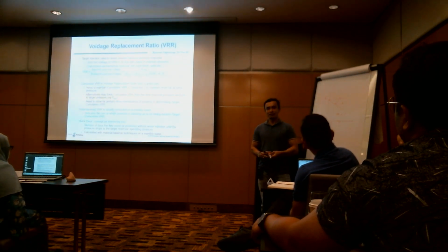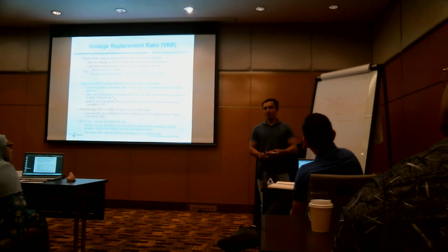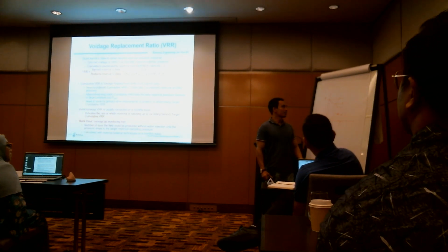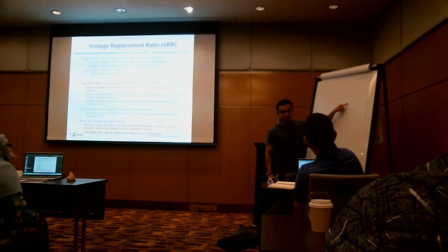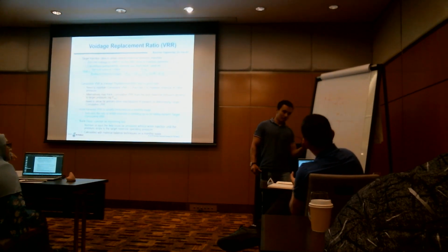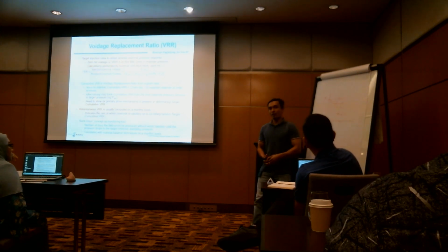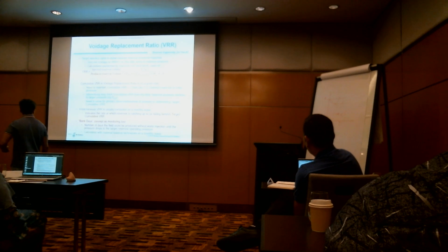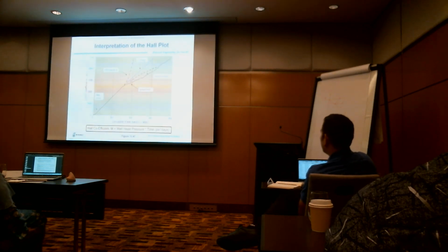So once you reach that original pressure, your cumulative VRR is about 1. If you just maintain VRR equal to 1, you will be flat at this level only, because your cumulative VRR is always below 1. This is an indication of being below the initial reservoir pressure.